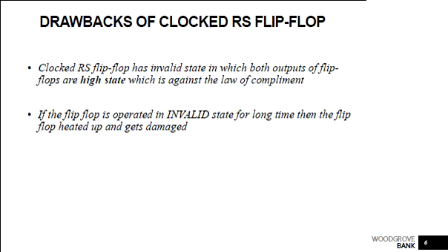When we discuss the drawbacks of the RS flip-flop, whether normal or clocked, there is an invalid state. When both inputs are high, we cannot define the output, so that is an invalid, forbidden state. If the flip-flop is operated in the invalid state for a long time, it can damage the flip-flop itself. So this is not favorable for a memory device. Then we need to consider a different type of flip-flop.